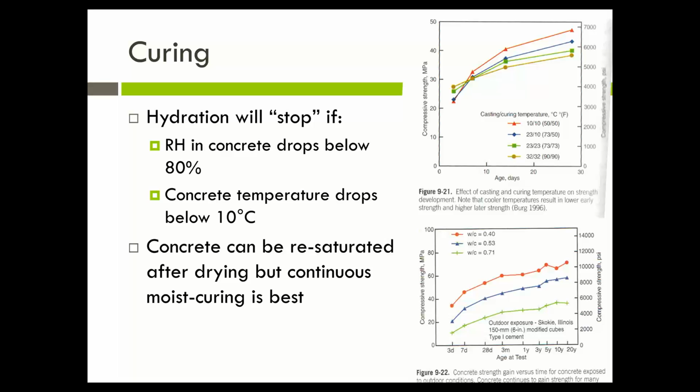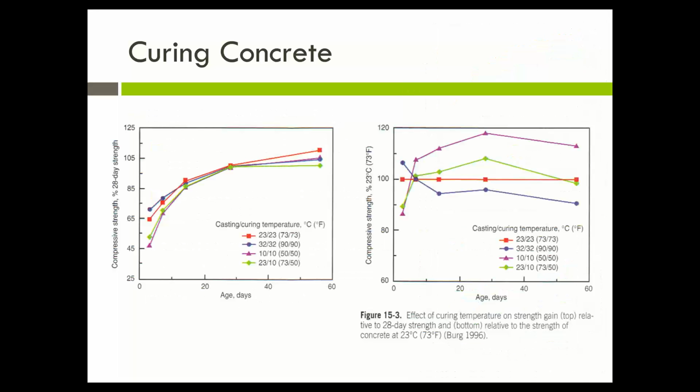If the concrete is dry and it gets re-wetted, then it will begin hydration again, but it's not the same as if it was kept moist continuously, because spaces in the concrete will dry out that you can't put water back into.